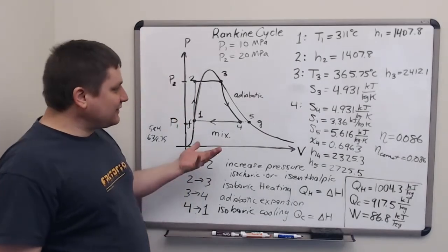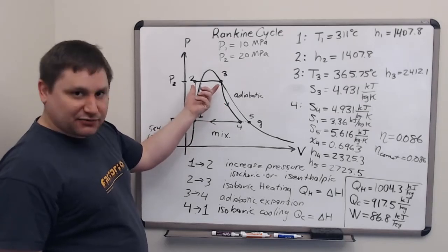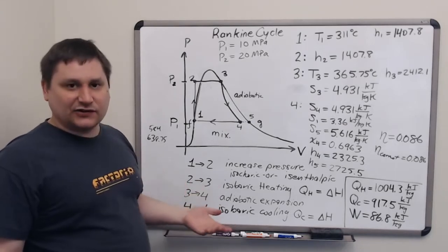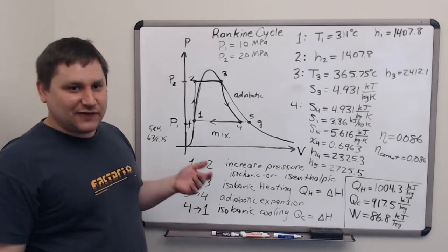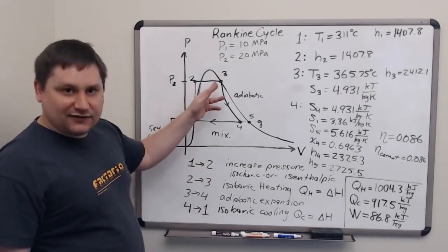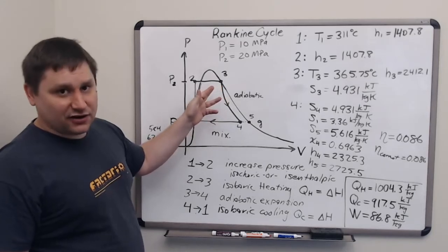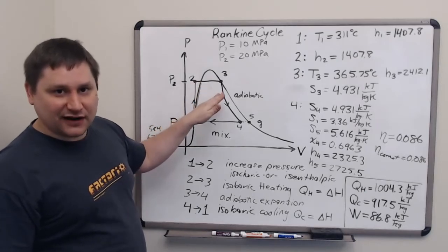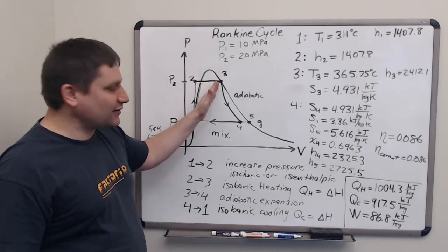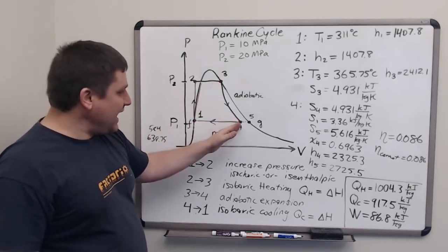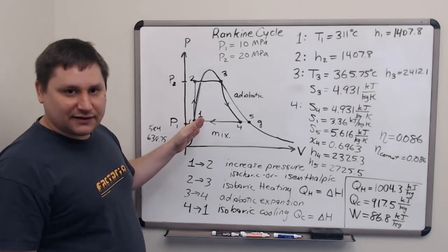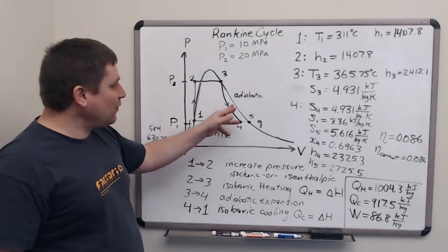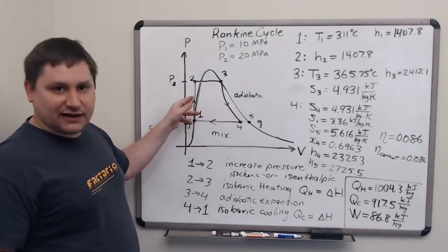So it appears that even though this Rankine cycle involves constant pressure and adiabatic steps, its efficiency is very close to the efficiency of a Carnot cycle. But if we think a little bit more about that, our steps under phase transitions do actually occur at constant temperature. So a Rankine cycle exploits the property of a phase transition to have a constant temperature step, an adiabatic expansion, and another constant temperature step at the bottom. This means that it's very close actually to the Carnot cycle with 2 isothermal stages, 1 adiabatic stage, and the other stage that is isochoric.